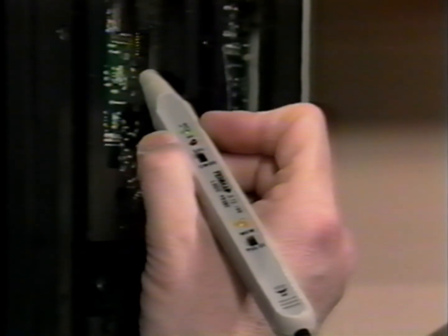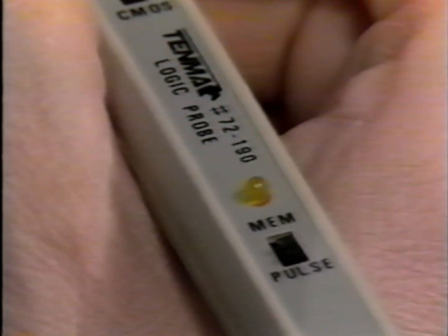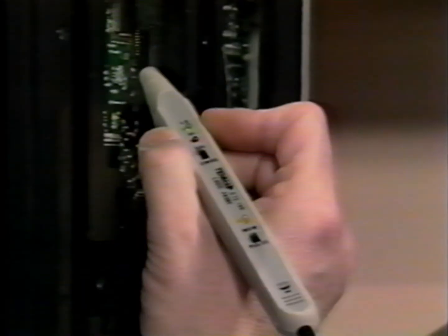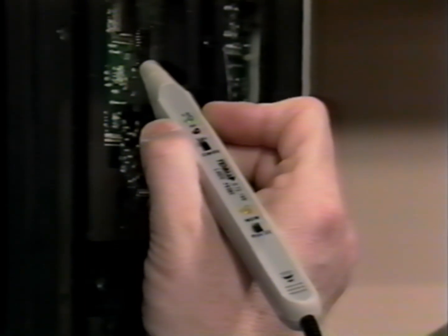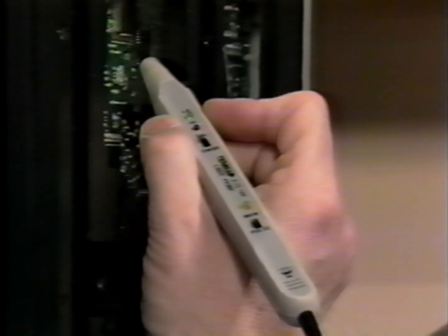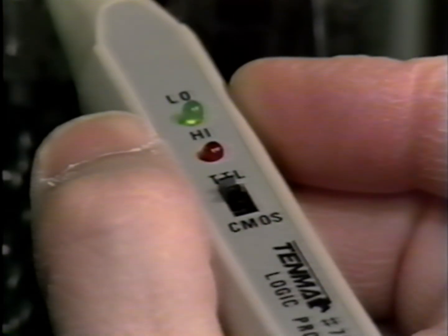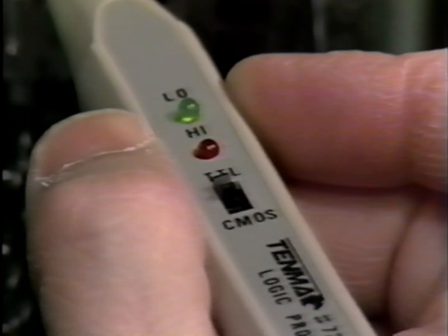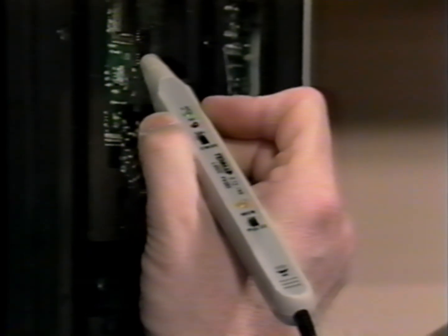When parallel data transfer is used, all of the data lines should pulse. Any line that is permanently stuck high or low probably indicates a problem. Keep in mind that a stuck line can be created either by the sender or the receiver or the physical data path. So be sure to check all 3 before changing an expensive IC.